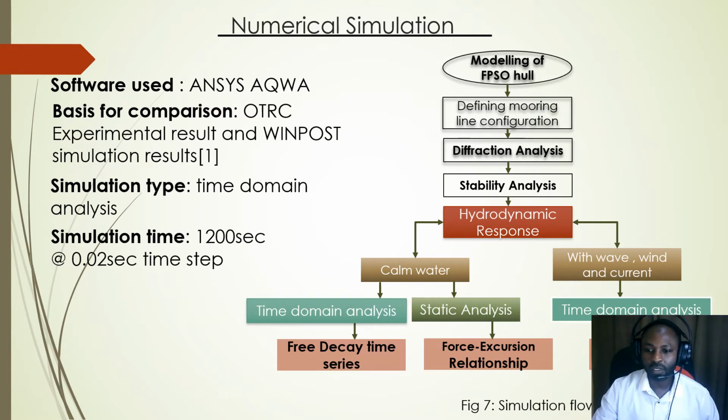First, we model the FPSO, then we define the line configuration, then diffraction analysis was conducted, from which we determine the hydrostatic forces, including diffraction forces, added mass and damping, then stability analysis, then the hydrodynamic response component of the software.